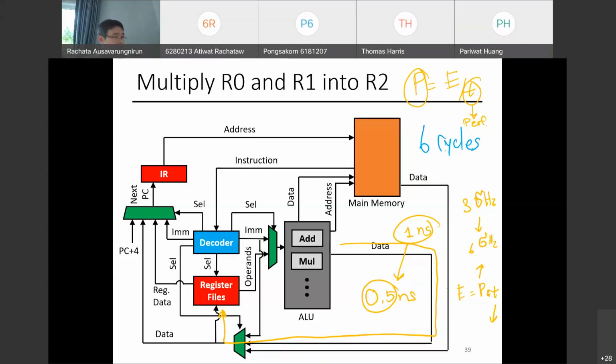On the low power CPU, it's the inverse of that. You make the input voltage low so that you can't clock it as high, right? To reduce the power. But your program might take a little bit more time, but it consumes less of your battery so that the battery lasts longer, right? So that's why I said it kind of depends.